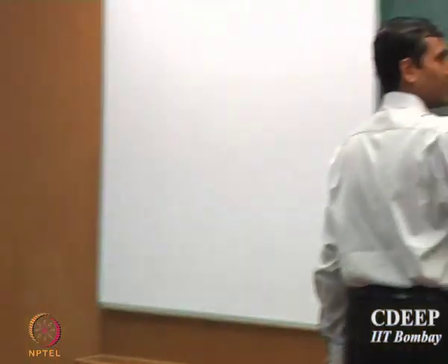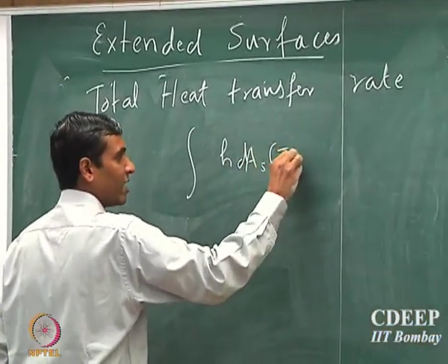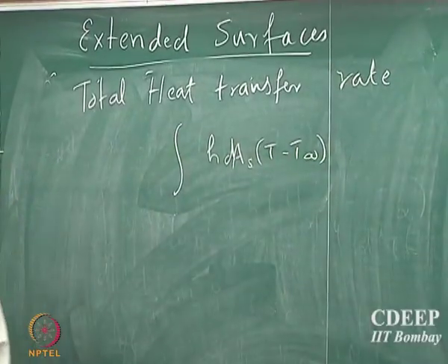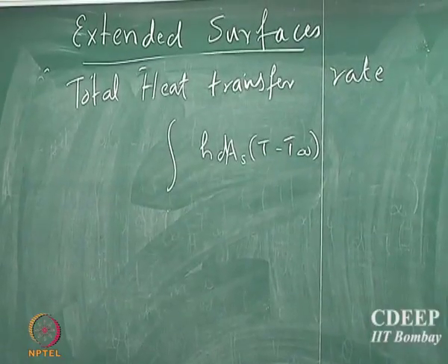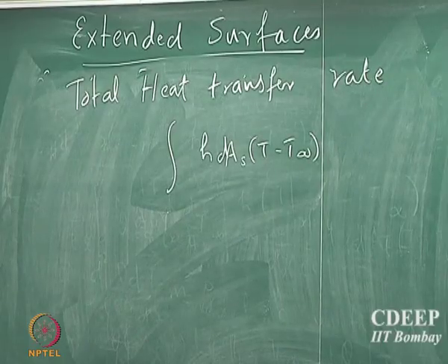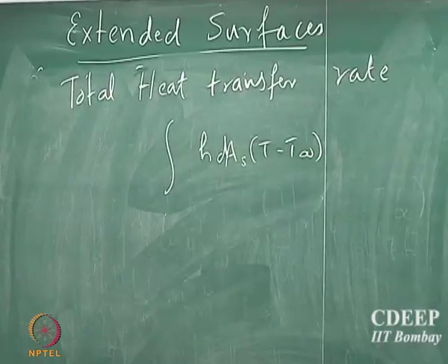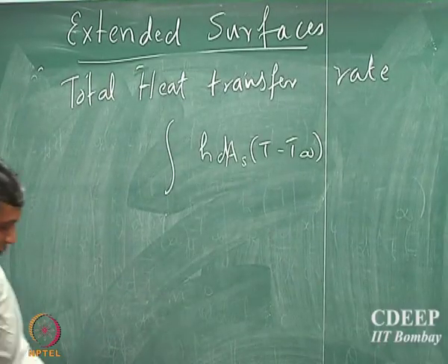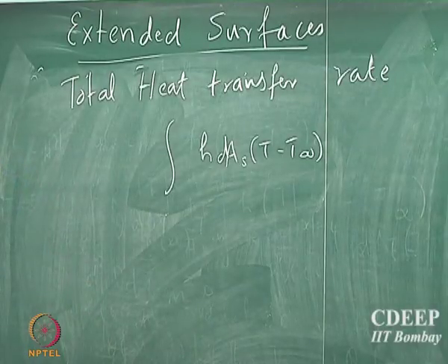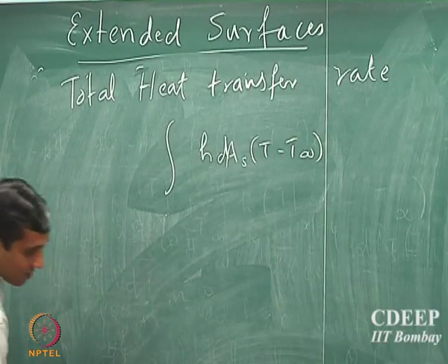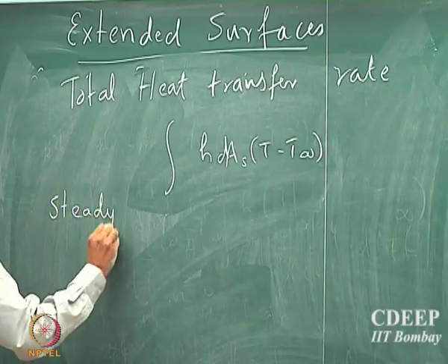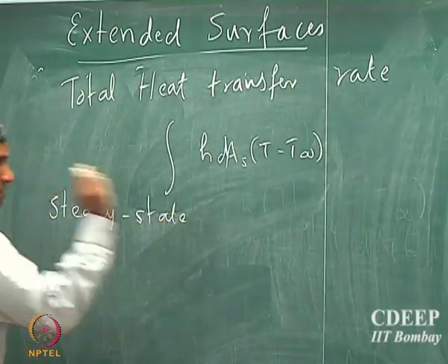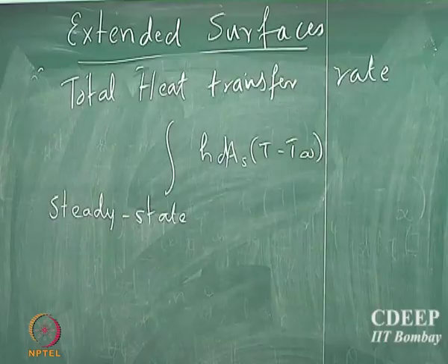So, one could integrate h into dA s into T minus T infinity, okay, across the whole fin. So, that will give you the total amount of heat that is transferred. So, that is one way to do that. But note that I always told you that you should use your intuition. So, there is an intuitively simple way to do this, okay. So, we assume that the system is under steady state, right. We said that the system is under steady state conditions.